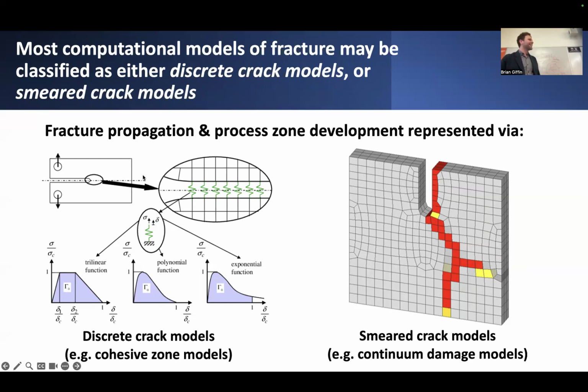It's kind of like we say that, at some interior interface, we insert a bunch of interface springs, if you like, that hold the interface together up until the point of fracture. And then once they exceed some critical threshold, those springs break apart. So you have to introduce these inter-element interfaces represented by these so-called cohesive zone elements or cohesive zone models, which are really nothing more than a fancy word for a bunch of springs. So just put a bunch of springs into your mesh that lose their stiffness as you pull the material apart. Simple enough. And in that way, you can emulate the behavior of fracture.